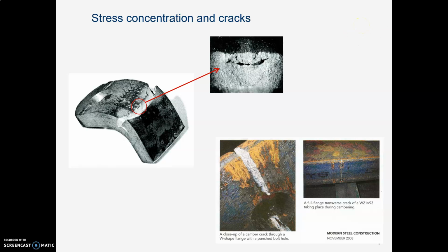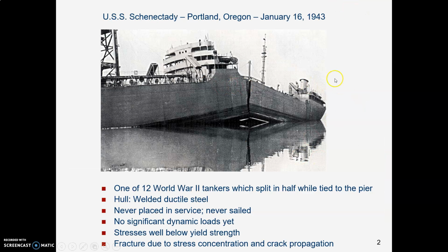We need to talk about stress concentration and how cracks propagate. I don't know if you've seen this picture of it. This was a tanker in World War II which split in half before it ever set sail, and it was due to stress concentration.